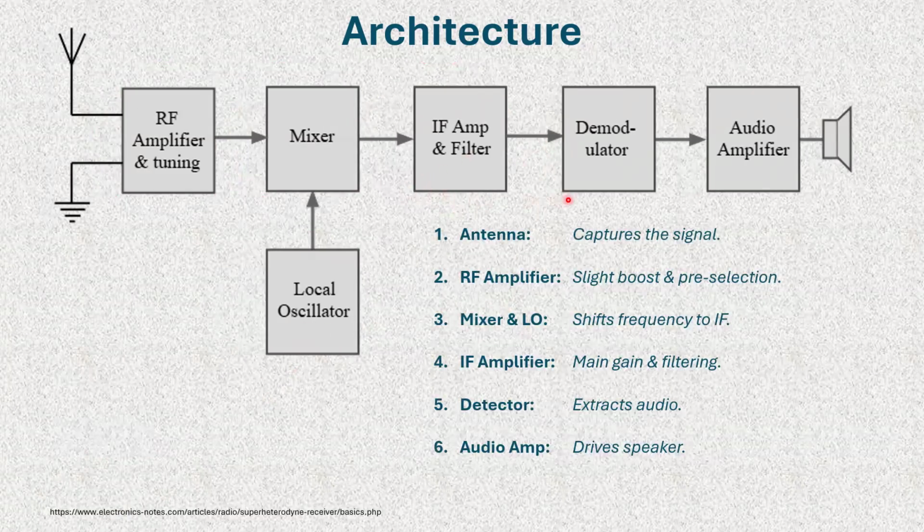So it's easier to design a circuit that works well with that specific carrier. The filters can be adjusted properly, the levels can be adjusted properly, because all it has to do is just be really good at processing one carrier. And that's when the quality of the whole transmission goes way up, when we only have to concentrate on that one carrier here, which is the IF carrier.